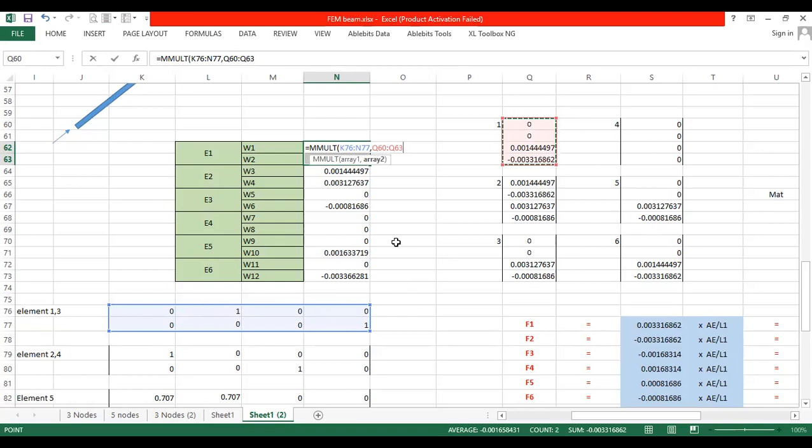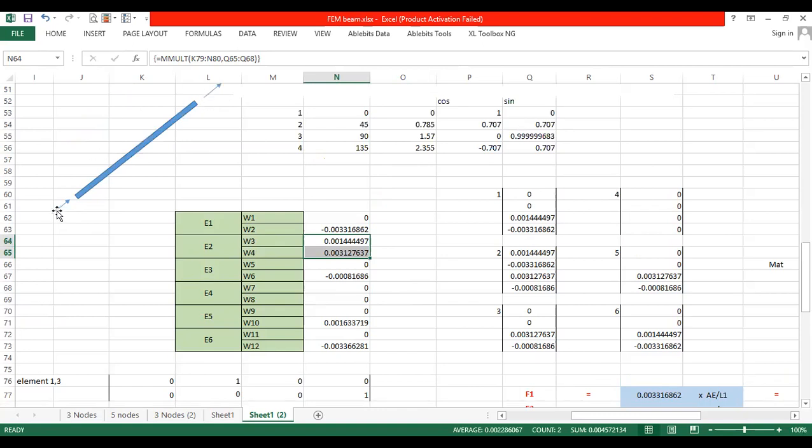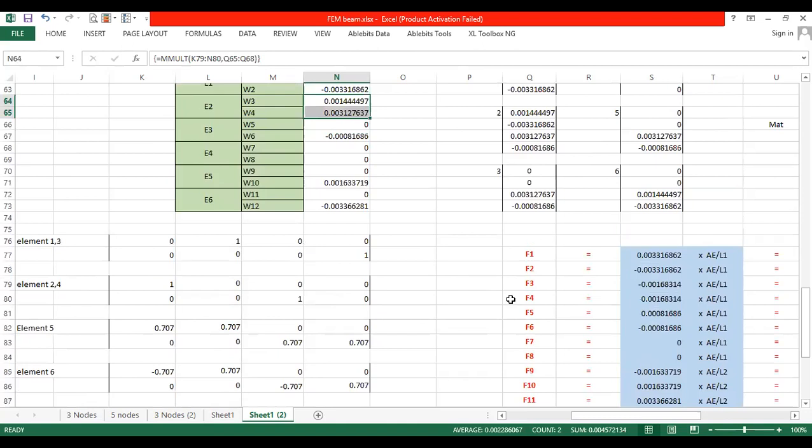You remember the sixth one is connected from 4 to 2. Then u4 v4 u2 v2. That order is essential. Here are your displacements. Likewise, you can get these displacements on a member. Once you get these, you can easily consider the forces.